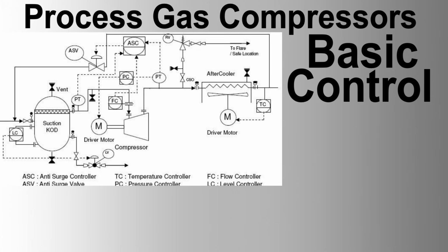B. Load-sharing algorithms. Develop load-sharing algorithms that distribute the total gas flow demand equally or based on the capacity of each compressor. Algorithms ensure that no single compressor is overloaded while others are underutilized. C. Synchronization. Ensure that the startup, shutdown, and operational synchronization of compressors are managed smoothly. Synchronize VFDs to adjust motor speeds of multiple compressors in unison.